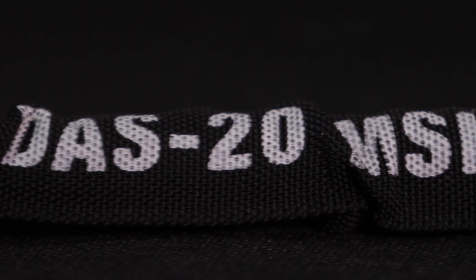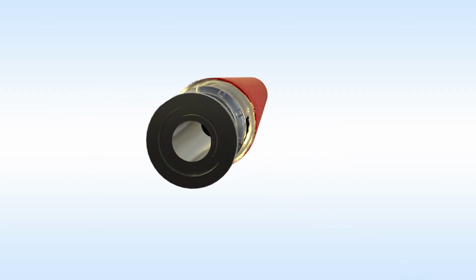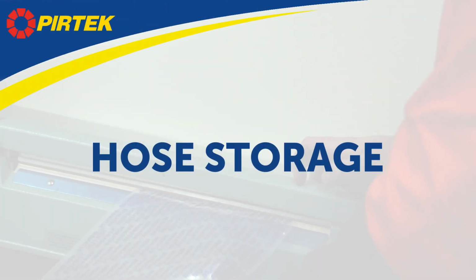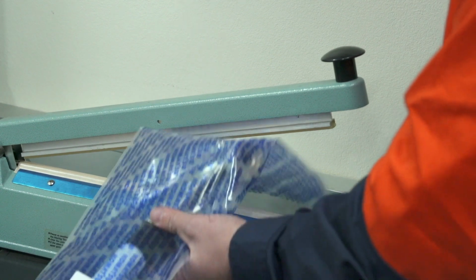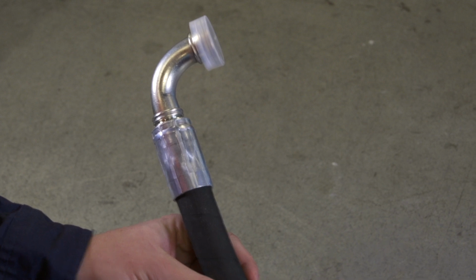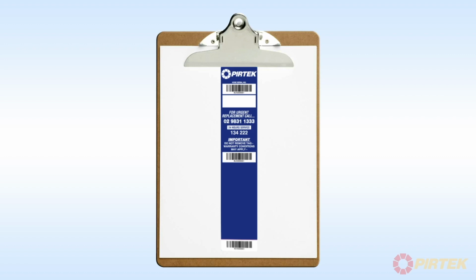These products are not a solution for a damaged hose, and it is not recommended to apply these products to a damaged hose. Hose storage. Storing a hose correctly can also prolong the life of the hose as well as keep it clear of contamination and remaining as new as possible. This can be achieved by the use of plugs, caps, heat seal caps, and bags.